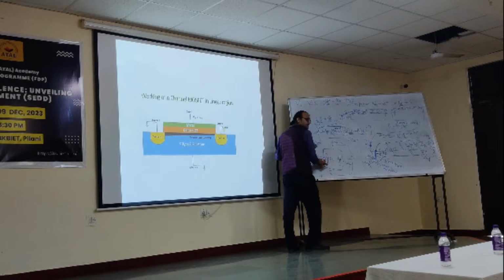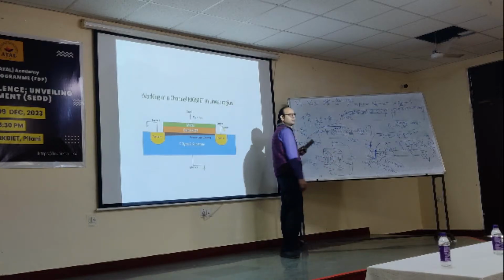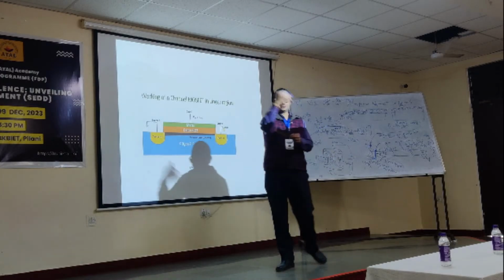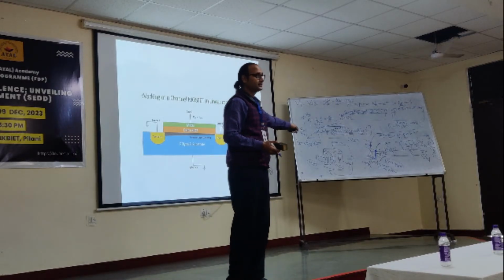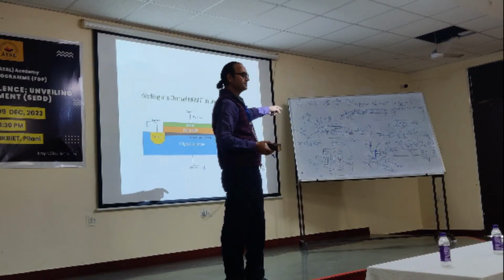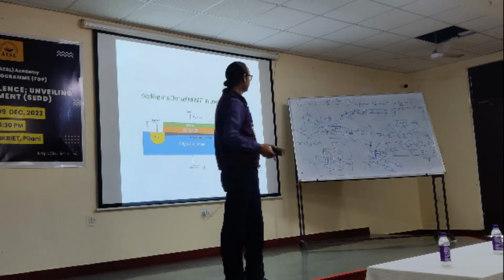This is reverse bias, obviously, because N is becoming positive and P is becoming negative. So it will get depleted. This will also get depleted. This depletion will increase with this negative bias, and a point will come when there is pinch off. The current saturates. But that is the case of FET, JFET, junction field effect transistor. Here we don't have those kinds of junctions.